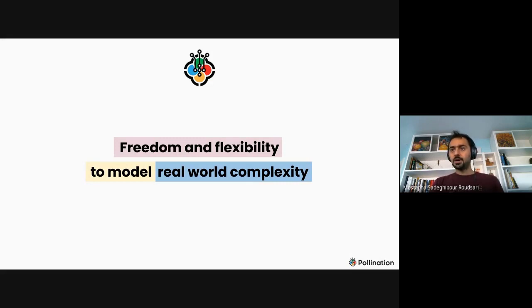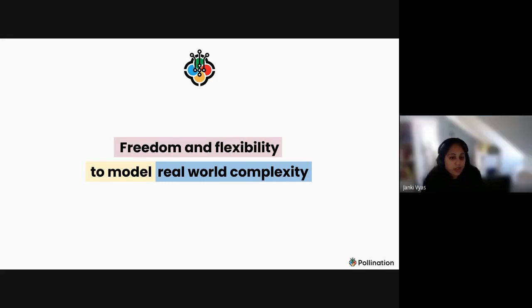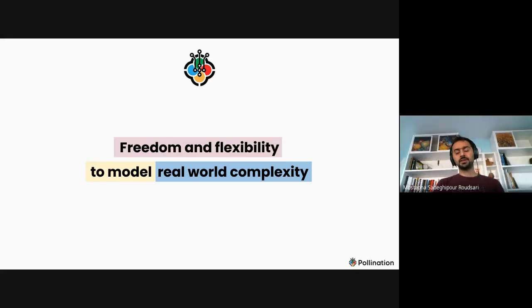Demi asks whether an area-based model means the floor area is accurate while the actual geometry of the floor might not be. Yes, that's correct. The floor area is accurate, and we do a good estimation of the volume. So the overall volume should be close to the volume that your room has inside the Revit model. She has a follow-up question: how do you deal with the wall thickness in that case? Revit does. When you export the rooms, you can select where you want the room line to be drawn. We just take the center for the interior walls and the outside for the exterior walls. But that's something you can change, and we can actually expose that.